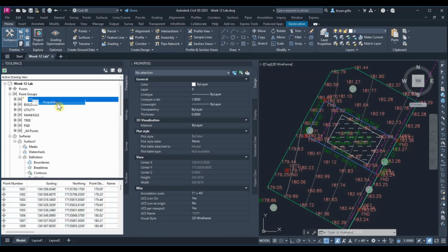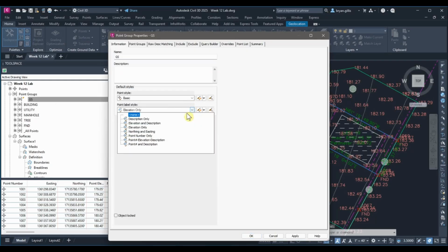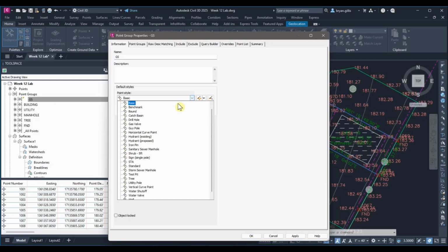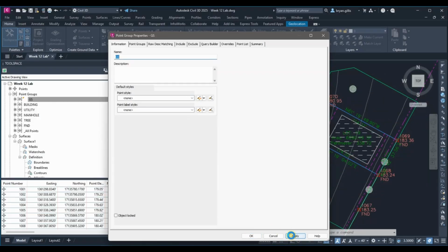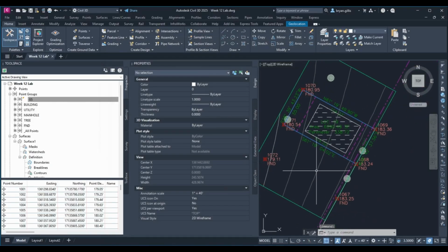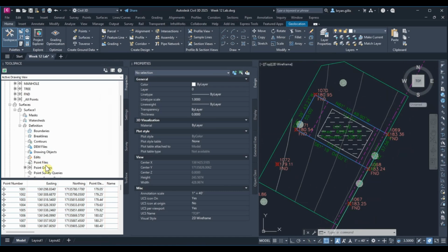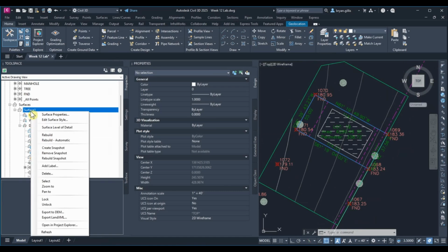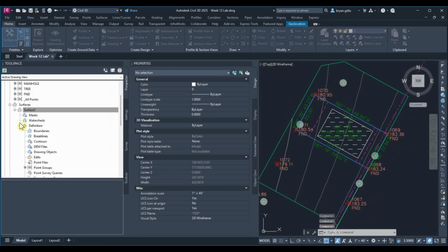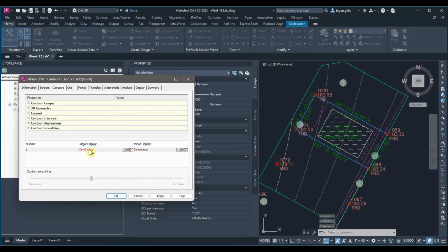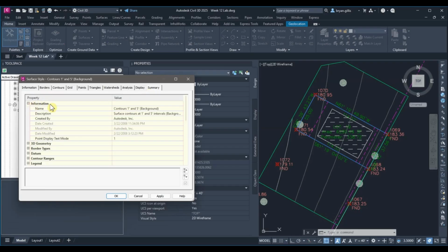So one of the things here, and I'm going to go ahead and turn off the visualization for the GS points right now since we have our contours going. One of the things we notice is we have a pretty steady grade going across our entire project. From this site, I'm not sure if it adds too much context for us, too much relevant information for our end user. So again, we have our 1 to 5 foot intervals. We could make it smaller, but I just am not sold on the idea that this is going to be a necessary visualization for our client.